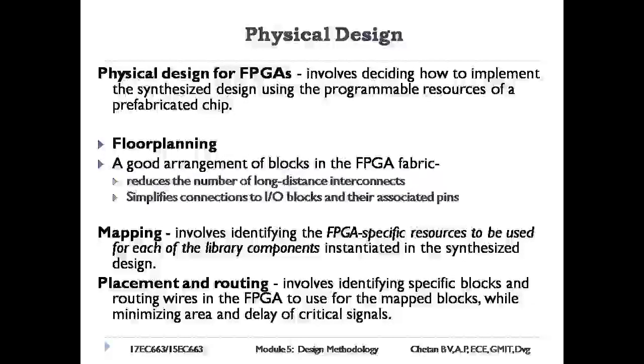Mapping. Mapping involves identifying the FPGA-specific resources to be used for each of the library components instantiated in the synthesized design. The result is an implementation of the design using logic blocks, I/O blocks, and FPGA-specific resources as opposed to the library cells used by the synthesis tool.